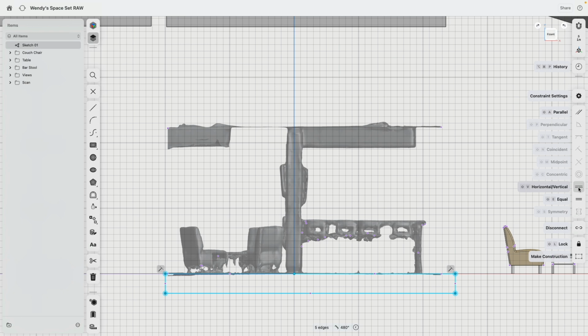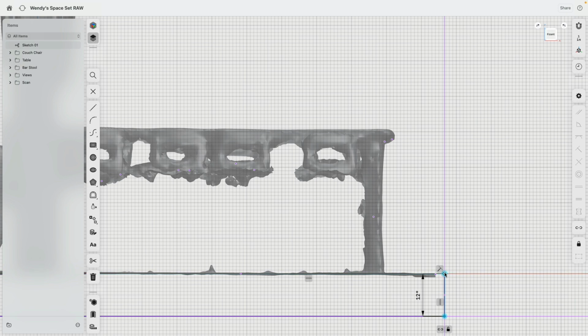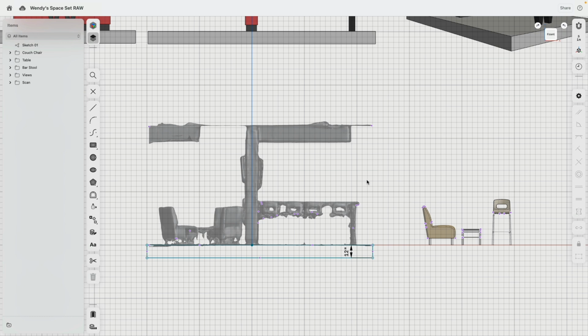Select everything, horizontal, vertical. We can make this foundation a foot, so 12 inches. Bring this over a little bit, let's say to there. This is really more representing the ground. And since we did this, it makes sense then to also draw what's there for the ceiling. A quick rectangle. I will specify this to 5 inches. And then here, this vertical distance, I make 112.5 inches.